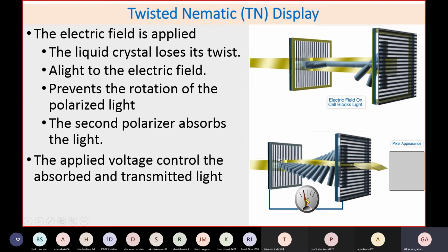But this is a very good picture which will give you the idea. Let us say this is vertical light coming through, as the LCD is in untwisted form. When there is no voltage applied across the LCD, this is the natural state, and because of this, your light is twisted by 90 degrees. If it is vertically polarized, it will become horizontally polarized, and when it reaches the horizontal polarizer, it will come out through it and your pixel will be brighter.